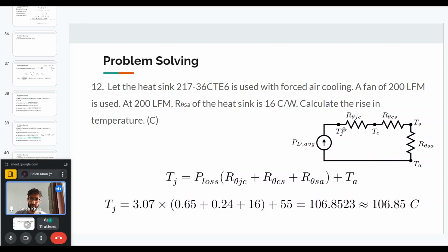In other cases, where we want very low thermal resistance of the thermal paste and interface material, there are different kinds of interface materials available. Again, it will depend on the thermal resistance of that interface material and the thermal paste. You can find out in the market what is available, the cost, and what your application requires.